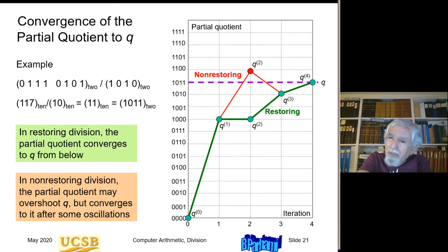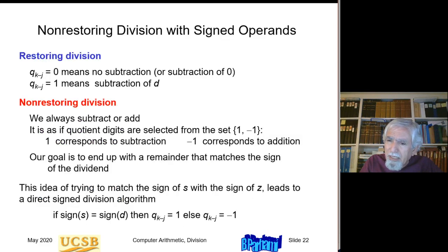So one drawback of non-restoring division is that at the very end, you need an extra cycle to make the correction in case the partial remainder becomes negative in the very last cycle, because there's no next cycle to add to make the correction. However, this may be worthwhile because each cycle in non-restoring division is shorter because of the removal of conditional dependency. And therefore, it may well be that 33 of those shorter cycles can correspond to less time than 32 of the longer cycles. Okay, so just because there's an extra cycle does not mean that it will be slower. It can, in fact, be faster.